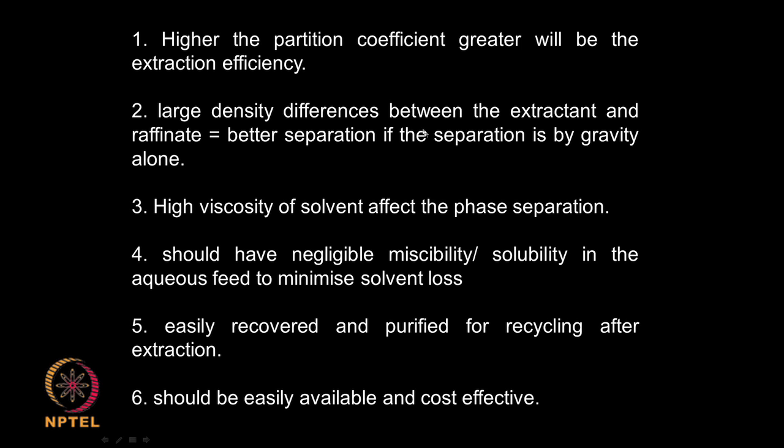Okay. So, the density plays a very important role, not in the first part of the extraction, but in the settling part of it. High viscosity affects the phase separation. If the solvent viscosity is very high, it is not going to immediately separate. They should have negligible miscibility, that means the solvent and the heavy or the raffinate phase should not be miscible. If it is going to be miscible, you are going to lose solvent. Okay. The solvent should be easily recovered and purified, because I cannot throw the solvent away.